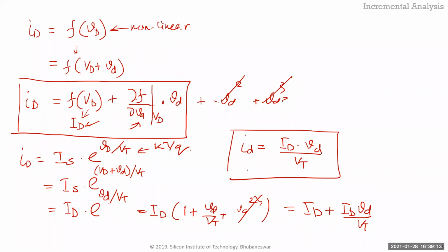So again, what I've done is I have taken the diode and done a small signal approximation, or a linearization of it, around the DC point ID. If the ID changes, then you have to go back and recalculate this bit. And what is this? This is just simply a resistor, right? Because if I take id times R, so what is R? Let's call it R incremental, which is equal to what? VT over ID, right?